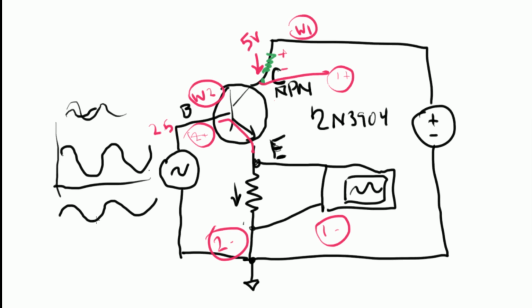So what we're seeing is basically this signal here. It's around 900 millivolts. We have a sine wave on that. And then once we open up the channel, so the VBE, this 900 millivolts plus this 1K resistor, so about 1 milliamp through here, it basically opens up the channel for VCE, and then that sine wave starts to draw current down through this resistor, in both directions. The sine wave is moving current back and forth across this resistor, and that's what we're seeing here at channel 1.